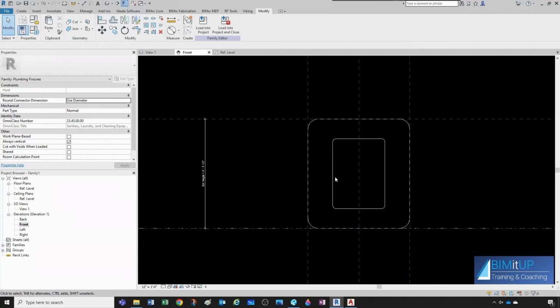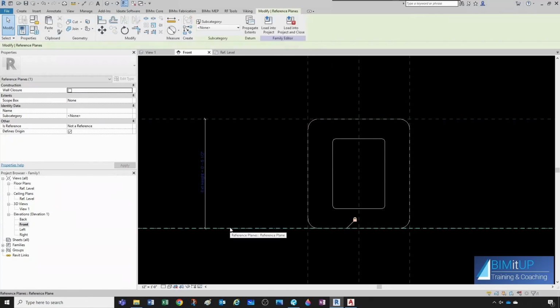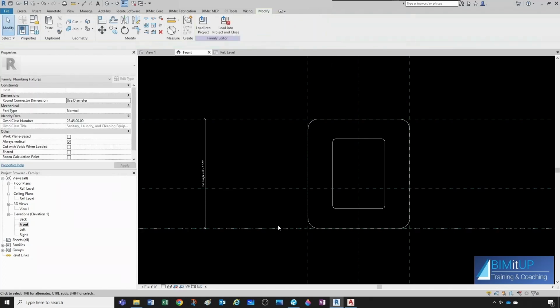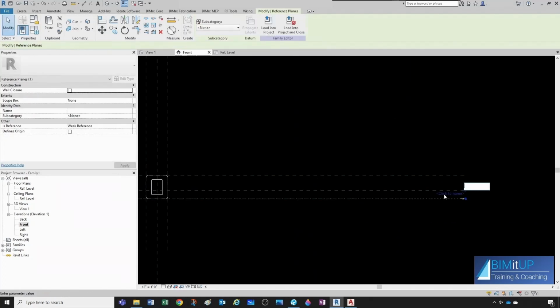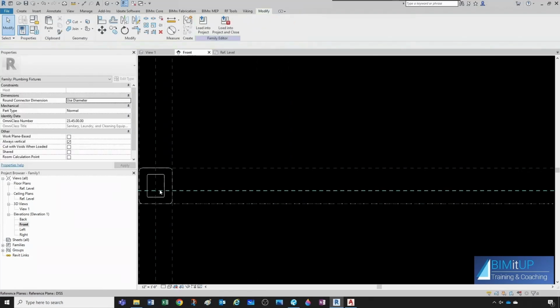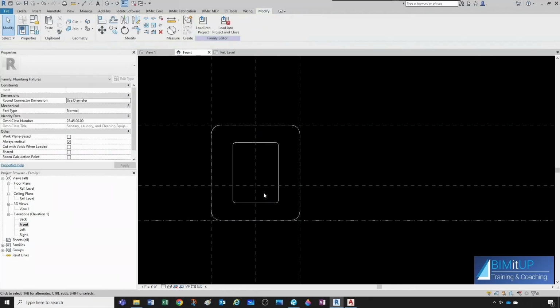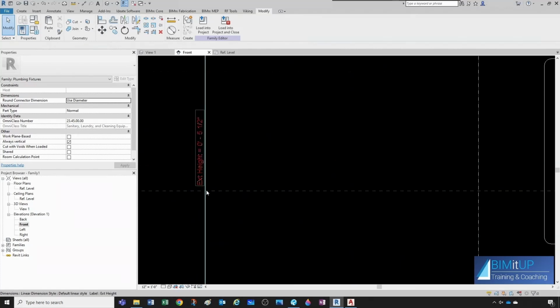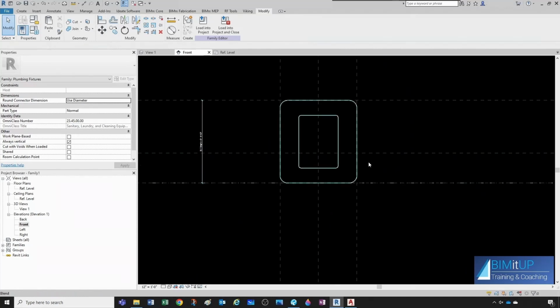We're gonna have to bite the bullet. Let's create a center plane right here. Okay, so tab select, create similar. So we pick plane 2 inches, approach it from the top, and then we're gonna call this DISS because that's where the connection's gonna be, and we want that distance to be half of the exterior height.